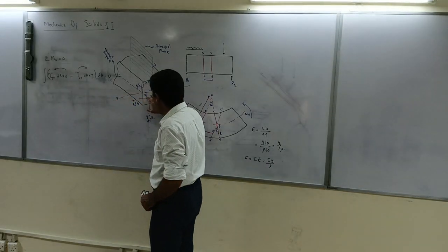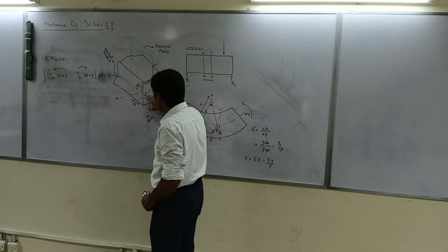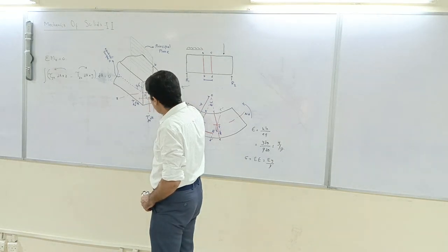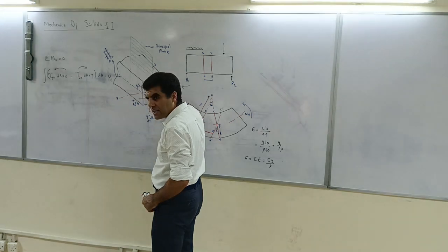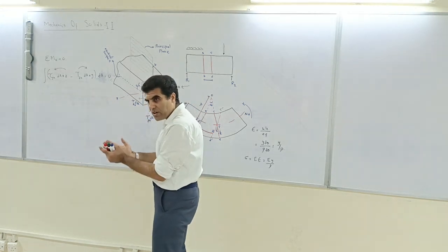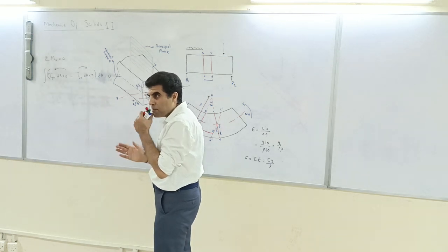Or say, z negative, if we say that this is our first order. This one, the same area, would have y positive and z negative. So this positive, that negative will cancel, and similarly these two will cancel. So your overall cross section is in equilibrium.